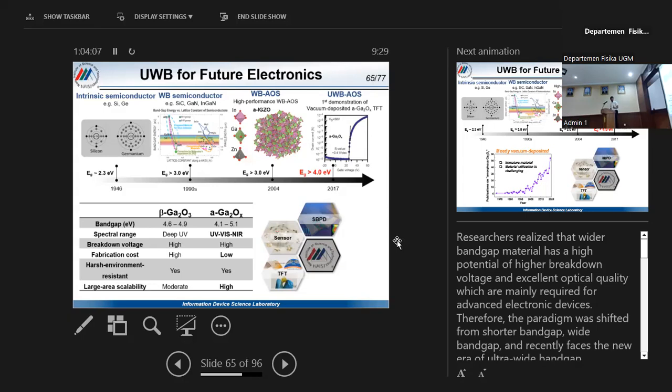So we did the plasma treatment without the CF4, only argon. And it's not limited to ICP; you can also use atmospheric plasma. I didn't show it here, but we also successfully used an atmospheric plasma system to functionalize or make oxygen vacancies in the semiconductor film. Thank you for the nice question.